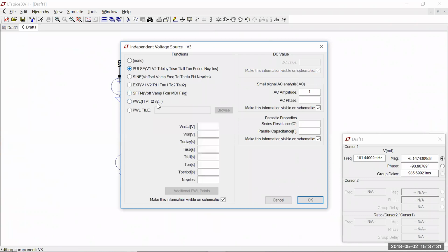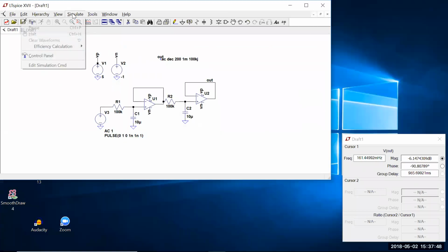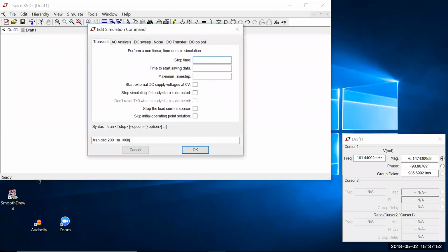Let's do a pulse, step response. We'll start it at 0. Since it's a buffer, it's not going to go above the power supply. I tend just to put in small numbers from here and then leave a large number there. All right. Now, simulate, transient. How long should I simulate for? Well, if a first order system had an omega naught of 1, that means tau is 1, I would simulate for 5.